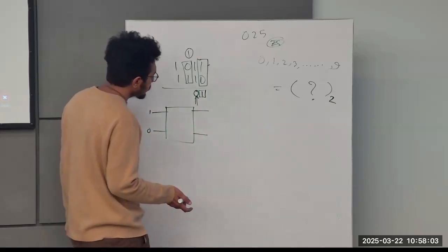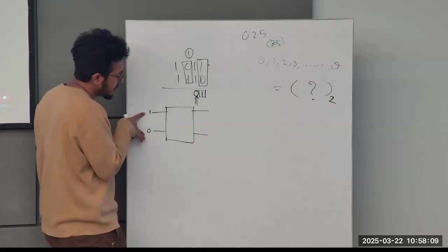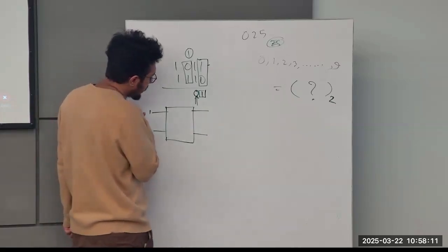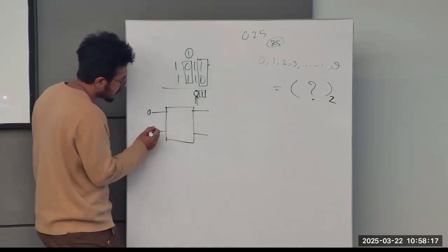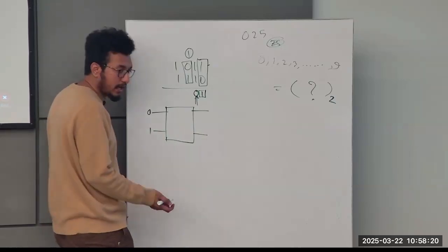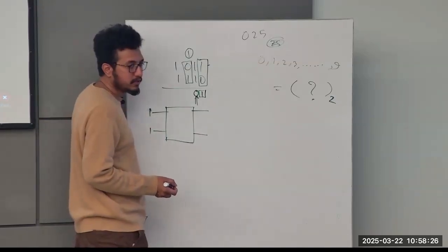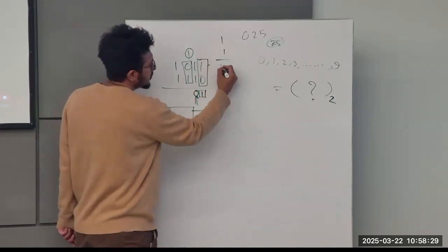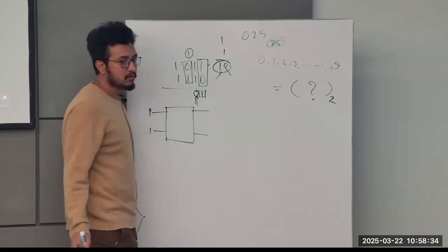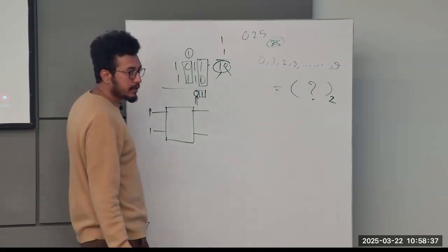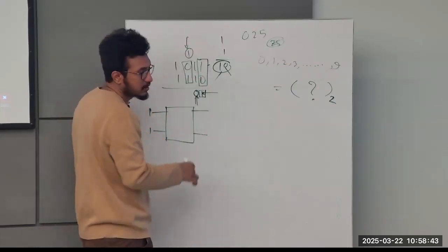So in your block, you will definitely have two outputs. I am repeating again. You will design a block that can add two binary bits. Now, obviously, when we have 1 0, we will have 1. When we have 0 1, the block will give 1. But when your block has 1 1, the output result will be what? 1 0. So you will basically need two outputs, right? One output like you will put here, and another output will be moved to the subsequent digits.